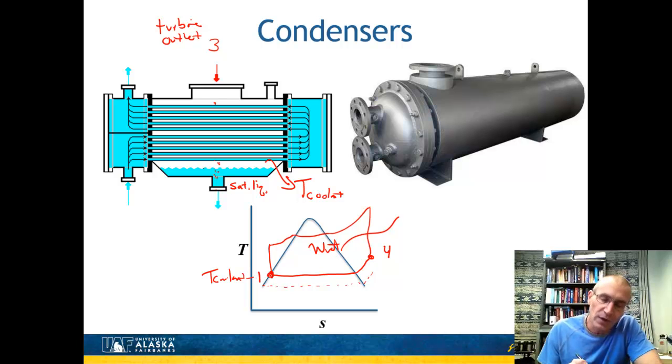the reason why this outlet is effectively always pinned to the left here as a saturated liquid, because that's what's dribbling out of here. It really doesn't become a condensed liquid, because as soon as it condenses, it tends to just drop off those pipes and dribble out of the system. So it's kind of a consequence of the way that the condenser looks.